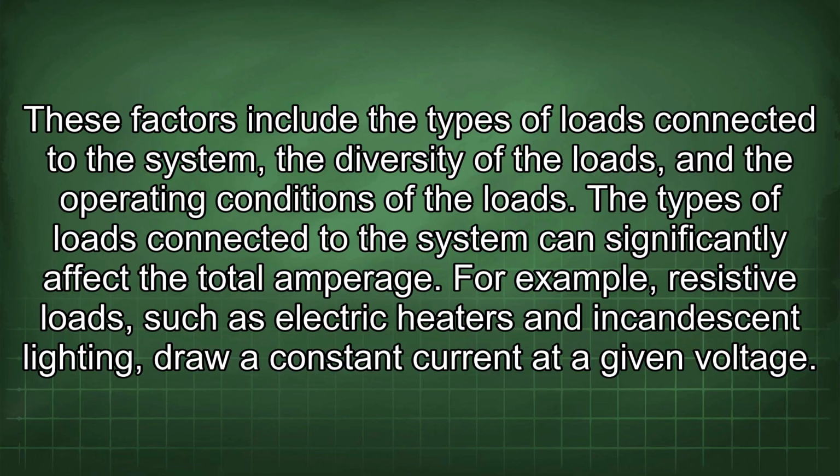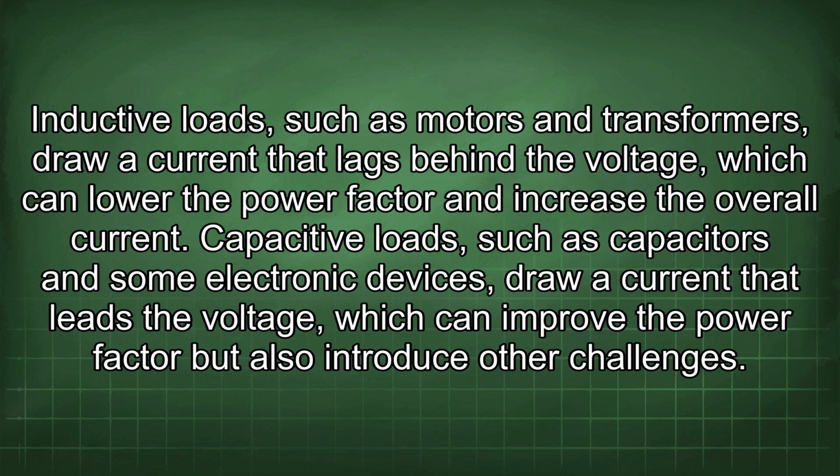For example, resistive loads such as electric heaters and incandescent lighting draw a constant current at a given voltage. Inductive loads such as motors and transformers draw a current that lags behind the voltage, which can lower the power factor and increase the overall current. Capacitive loads such as capacitors and some electronic devices draw a current that leads the voltage, which can improve the power factor but also introduce other challenges.